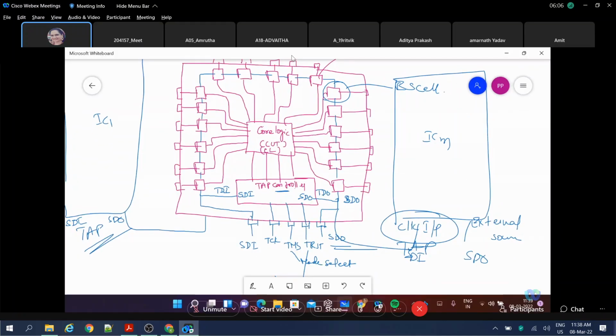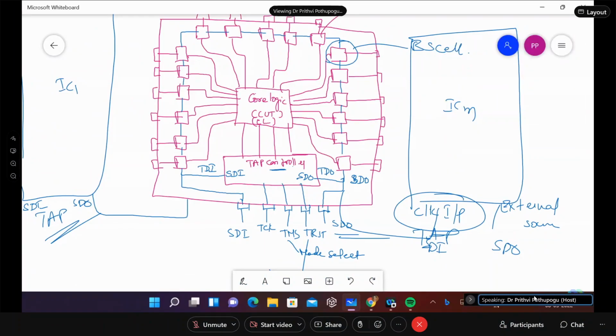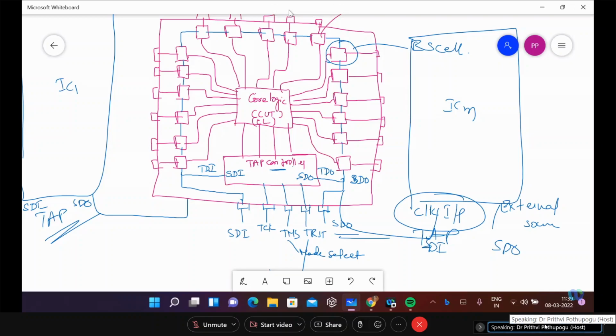Test and maintain the circuit functionality. Okay, so, a position of what we say a scan testing we have seen, where scan path testing was there when we interlink all the flip-flops from one stage to the other in a chain fashion. That is scan path testing.